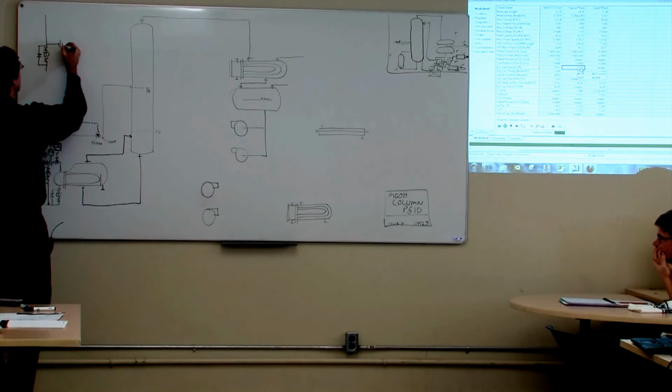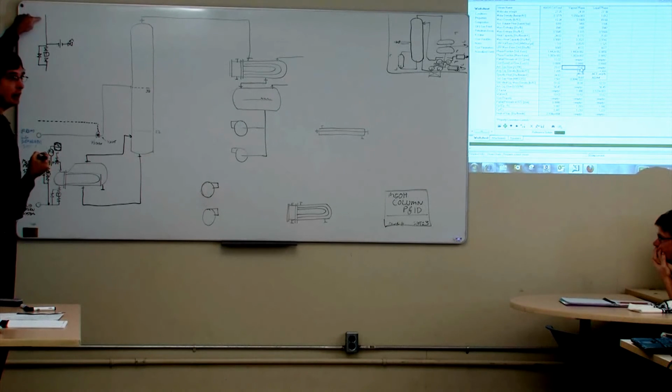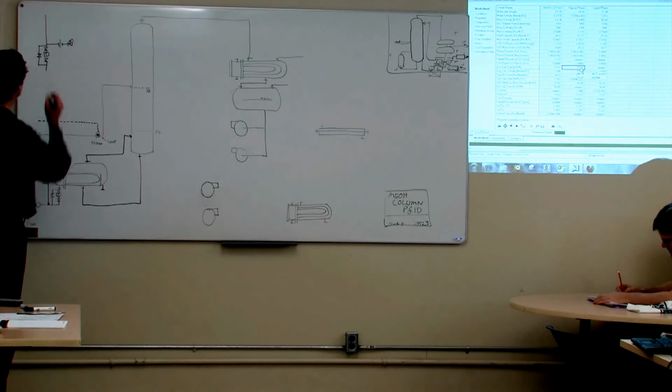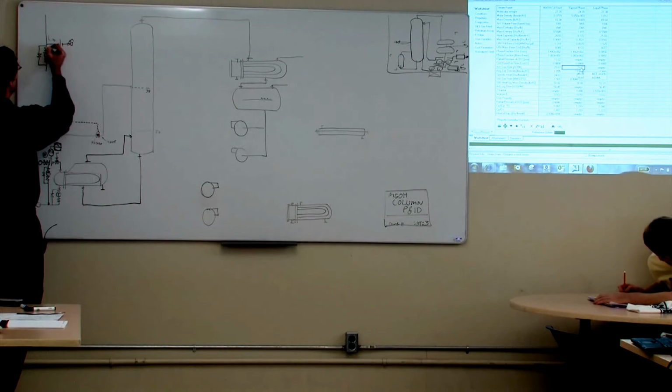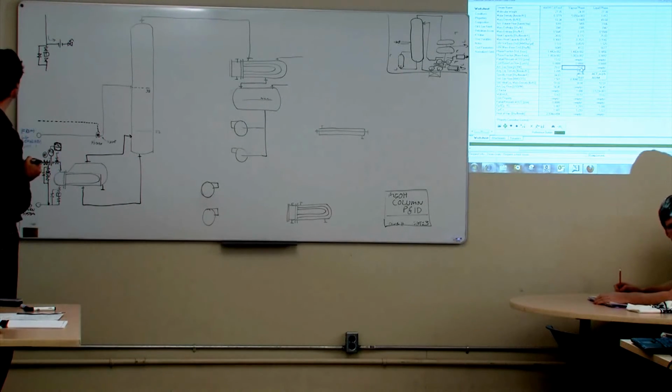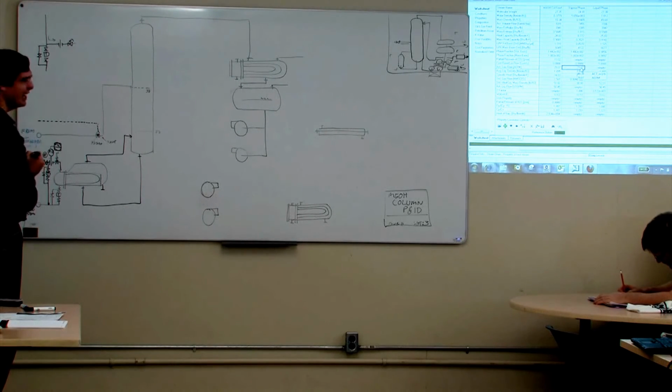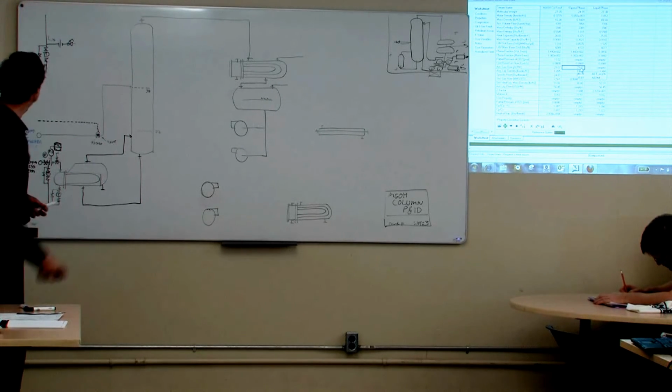And then you'll go off to your process like this, so that the momentum of the water and the steam basically carries it down into that T, and it throws the water up against that system. I know that doesn't explain it very well. Can you kind of picture the momentum? If the steam is having to change direction, the water is going to keep on going. It throws it into the steam trap system. Does that answer your question? Not really, eh? No. Let's talk about it later then. Okay.